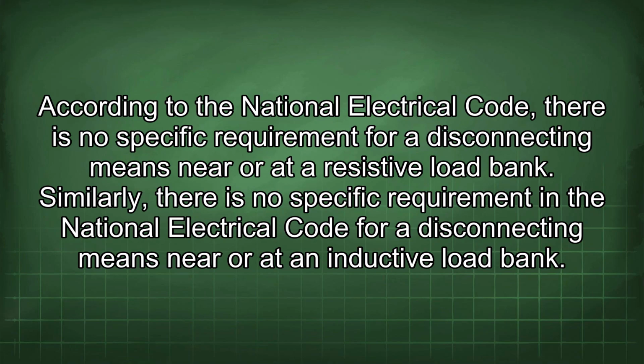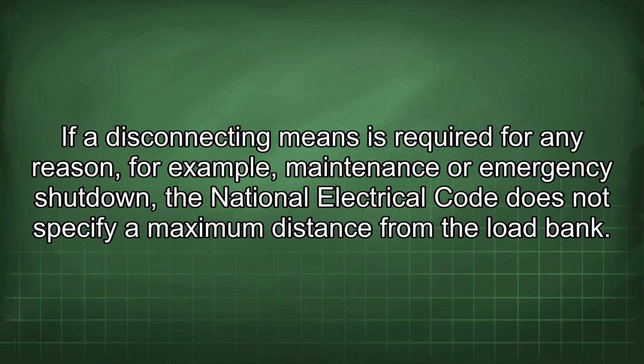According to the National Electrical Code, there is no specific requirement for a disconnecting means near or at a resistive load bank. Similarly, there is no specific requirement in the National Electrical Code for a disconnecting means near or at an inductive load bank. If a disconnecting means is required for any reason, for example, maintenance or emergency shutdown, the National Electrical Code does not specify a maximum distance from the load bank.